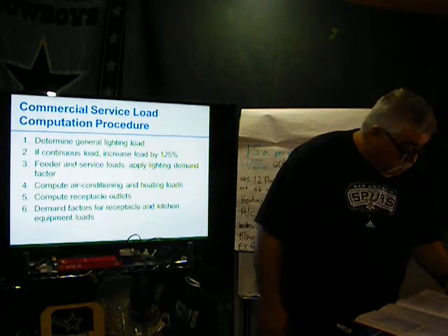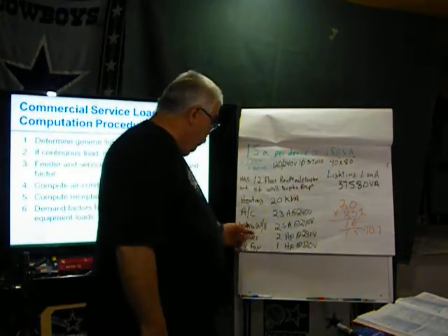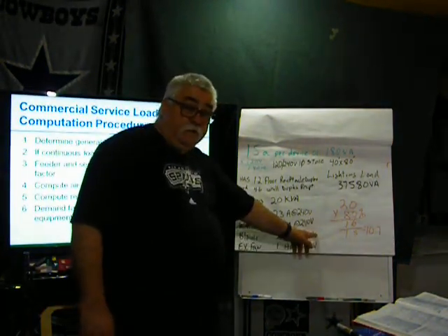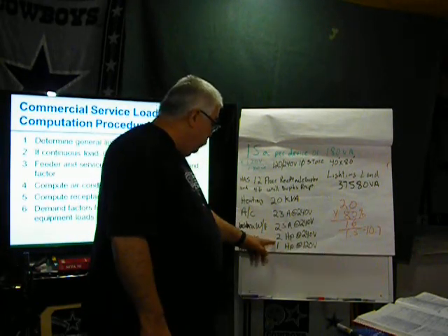Increased motor, if you got two motors. So some of the questions were, okay, because I got two motors, do I multiply one times 125% and add the other? No, because these are two separate motors.